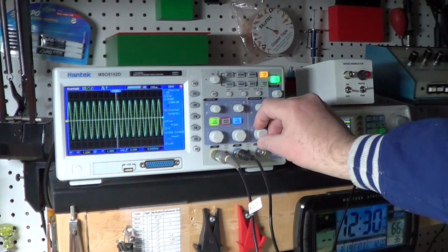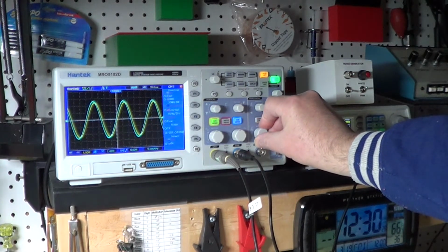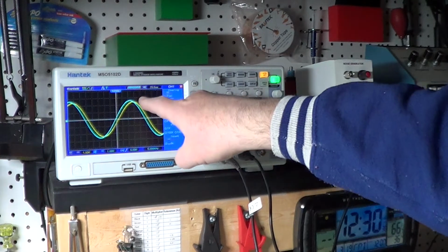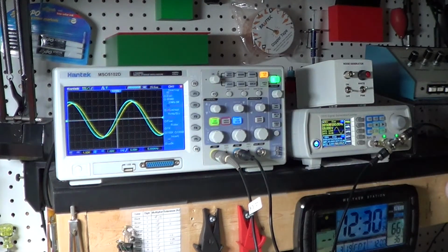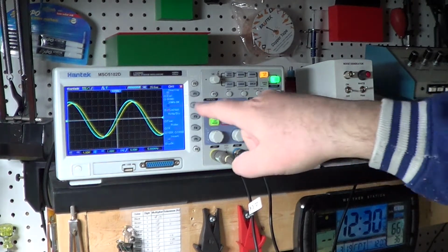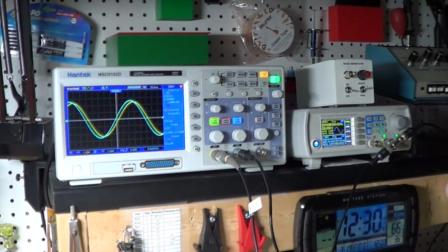Let me change the scale here so you can see better what happened to the sine waves. You see what's going on? The output level is reducing, but just a little bit for now. But at the same time it is also shifting with respect to the input, and that's because of the capacitor, which introduces a shift between the current and the voltage, and in particular the current is anticipating the voltage.